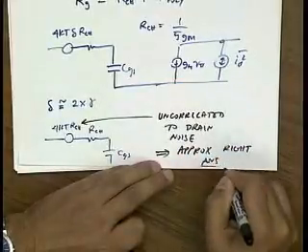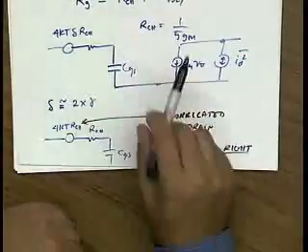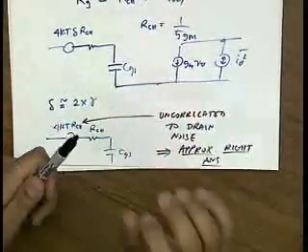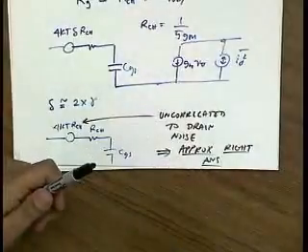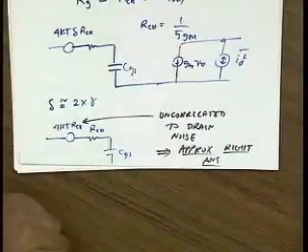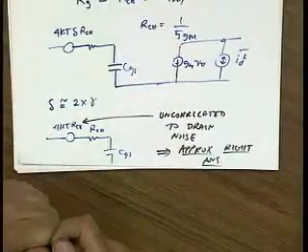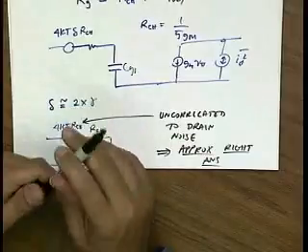So it turns out that the easy solution gives you the right answer. If you do the hard way and take the correlation into account and everything, you get a slightly more accurate answer, but believe me, it's a lot more painful to arrive at. So this approach is a very nice way of handling the MOS noise, gate-induced noise. You just assume it's uncorrelated and you get rid of this factor delta. Okay?